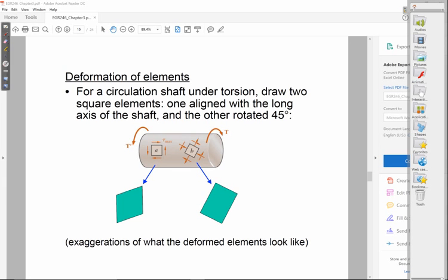Concrete is used to support bridges where they're only in compression. If there's any possibility of the concrete going into tension, then you wouldn't use pure concrete. You would start embedding steel rods inside that concrete, what we call rebar.